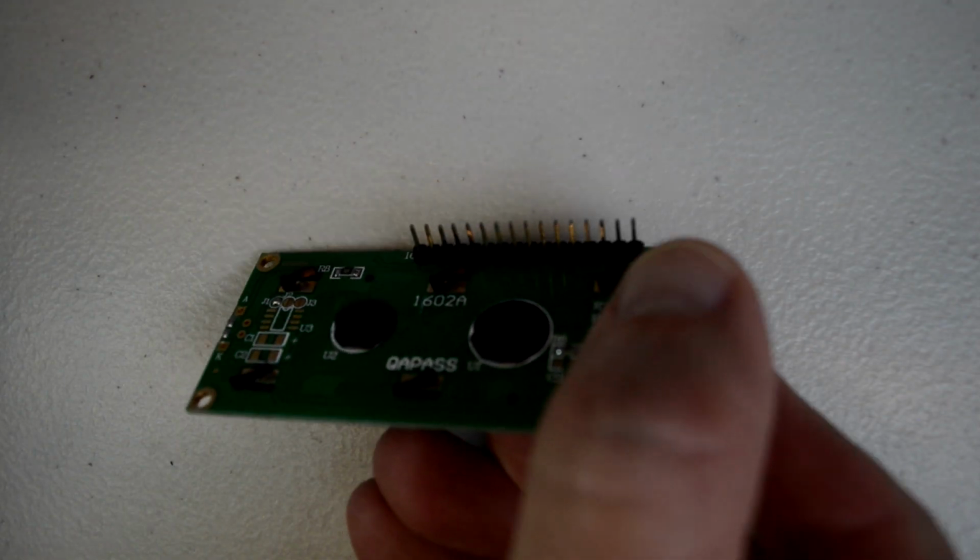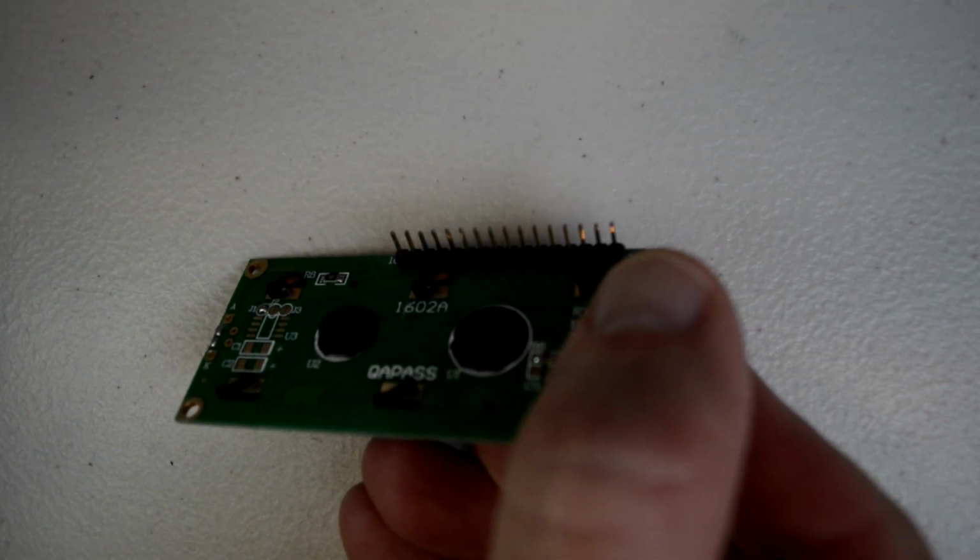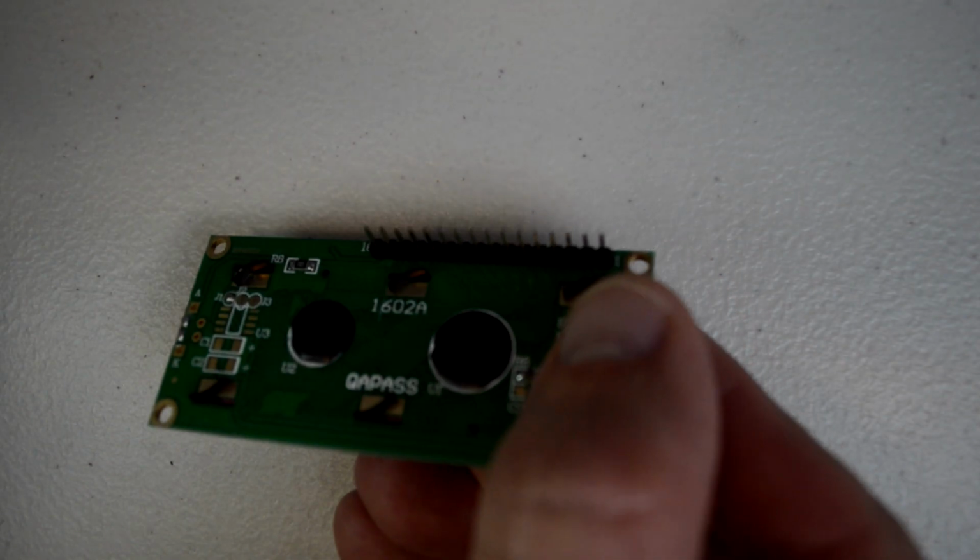First off, here we see a standard LCD1602 module, which is a liquid crystal display consisting of 2 rows of 16 characters, hence the name. It has an LED backlight. This module came as part of one of my Elegoo Mega starter kits. We can see it has a pin header here, already soldered in place, and this makes it very convenient for use with a breadboard.